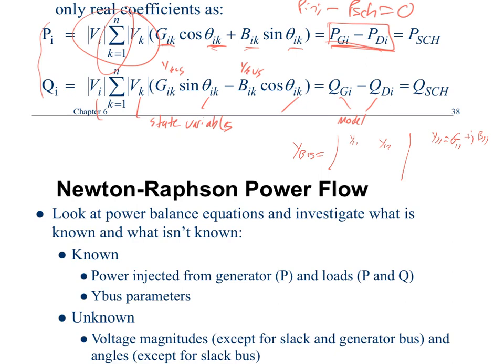Remember, and I was doing this very specifically, and I talked about this in the last class, you will note that B11 does not contain the j term, does it? I pulled it out separately from there. So your B term should never have the j term in there. You should strip it out. Because if you do that, the Q equations and the power equations now have real and imaginary parts. What we did when we built our P injection equations is we multiplied everything out and then we factored it into the real and imaginary terms. So we've already stripped out the j terms in advance. You don't have to worry about that. That's been done for you. But do not put those in there. Okay?